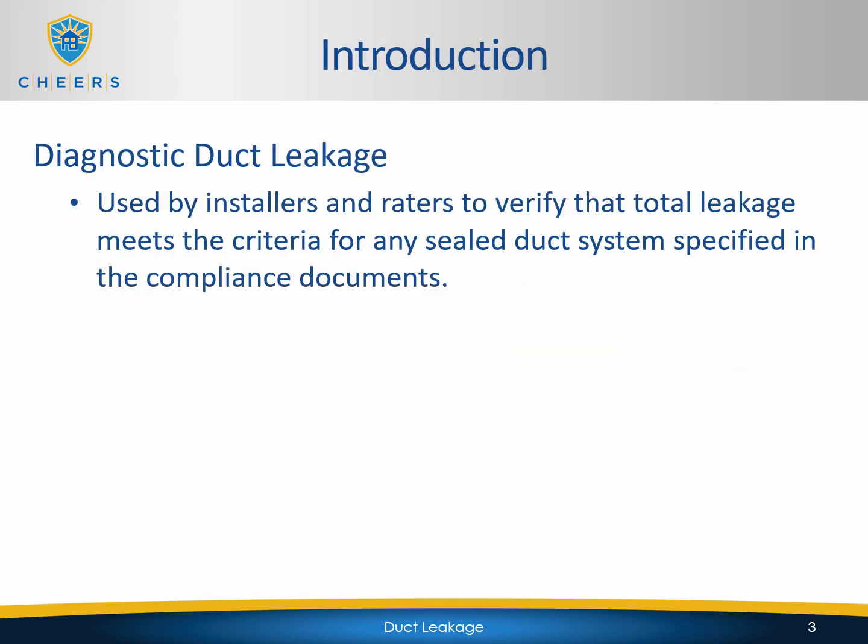So diagnostic duct leakage is used by installers and raters to verify that the total leakage meets the criteria for any sealed duct system specified in the compliance documents. So it's the overall leakage of the system compared to how much air the system is actually supposed to supply.